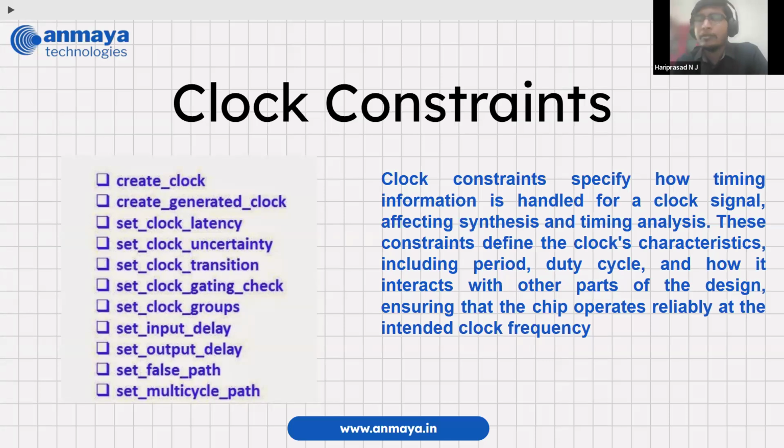That's it. Architecturally, we have to resolve it using the synchronizers we discussed for multi-clock designs. A few of them we discussed: toggle synchronization and FIFO-based synchronization. Using that methodology, we have to resolve it. But after designing all the synchronizers and architecting properly, if you are still seeing a timing violation, it might be due to improper information given to the tool itself.